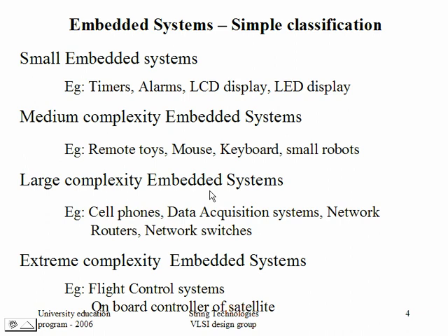Whenever your requirement is only reading the data from some sensors and updating to some other sensors or other ports, a microcontroller is well suitable. But let's say I have some requirement where I am not only reading and writing the data, a lot of processing is involved. We obviously prefer a microprocessor based embedded system. Today, the majority of embedded systems, which come with ARM processors and all, actually fall into this category.